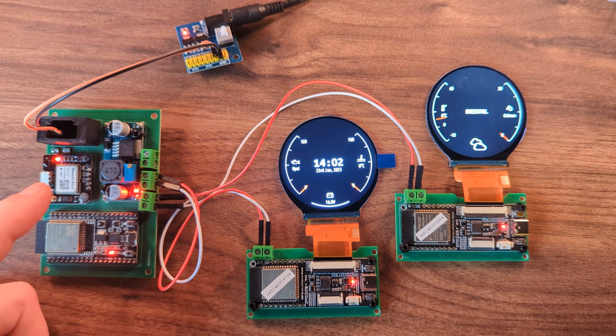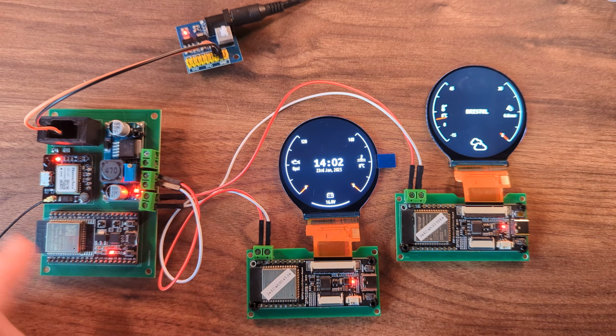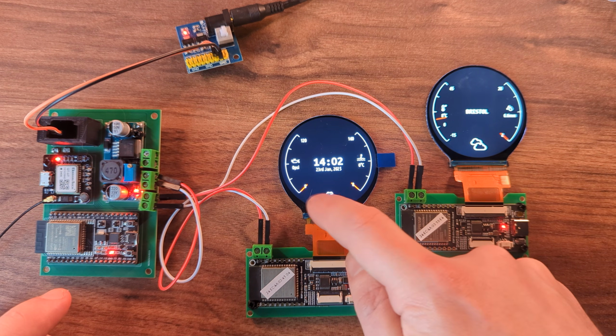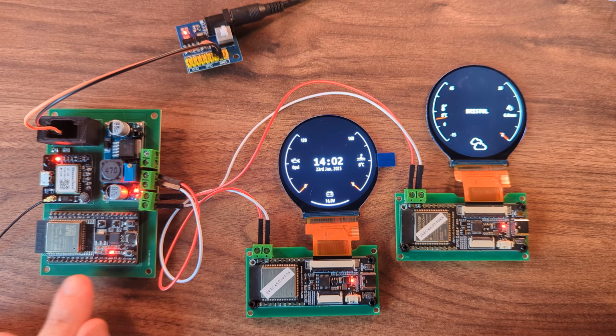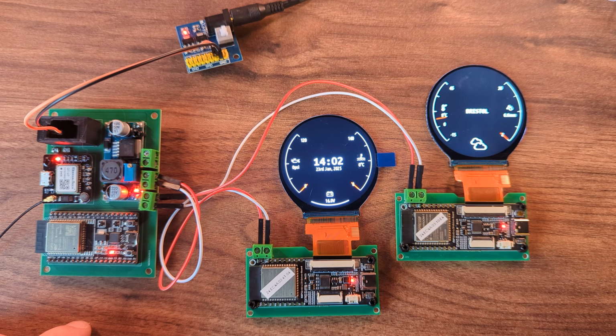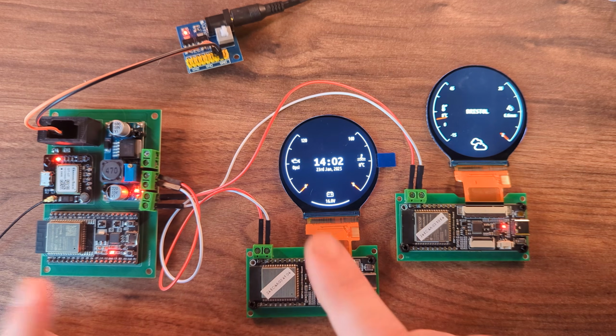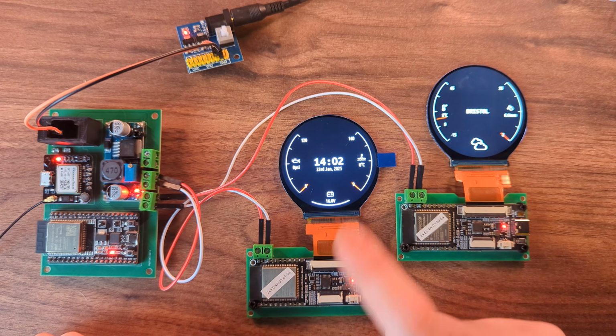At the moment, the pressure that we will be hooking up to the pin in here is coming through to pin 32 over there. At the moment, that information is being ignored, so the code hasn't been written in here to create this oil pressure graph. So the ADC signal in here isn't being converted to a number to allow it to be used on this pressure gauge. So what we need to do is set up this pin for the ADC for oil pressure, convert it using the right formula to do ADC conversions back to a voltage, then onto a PSI, and then broadcast that with the rest of the information that's going out onto this screen.